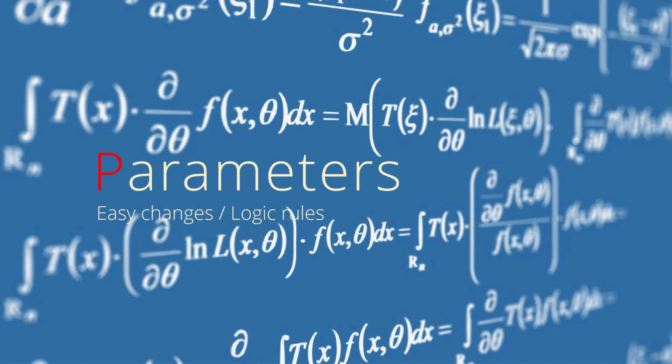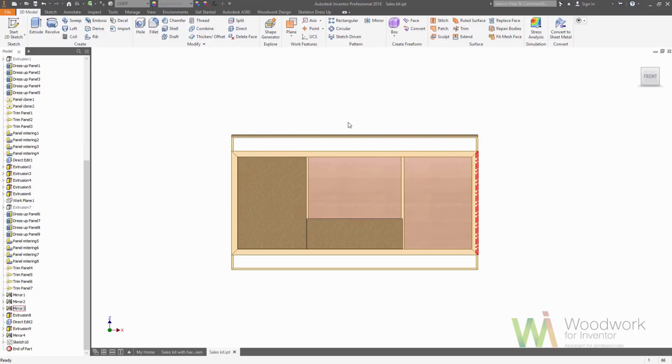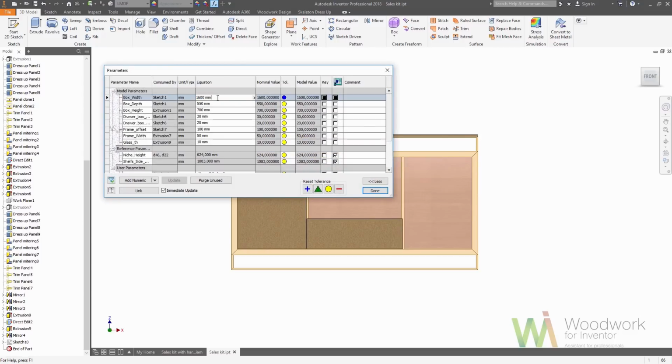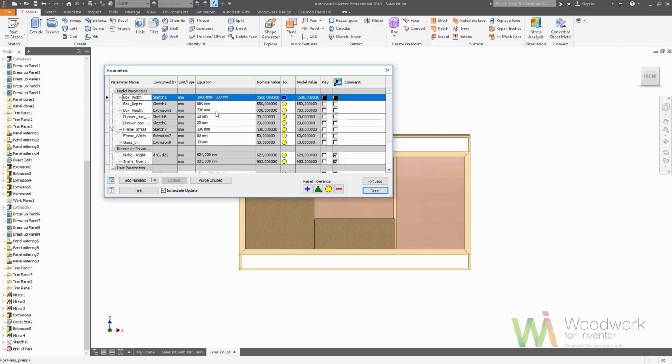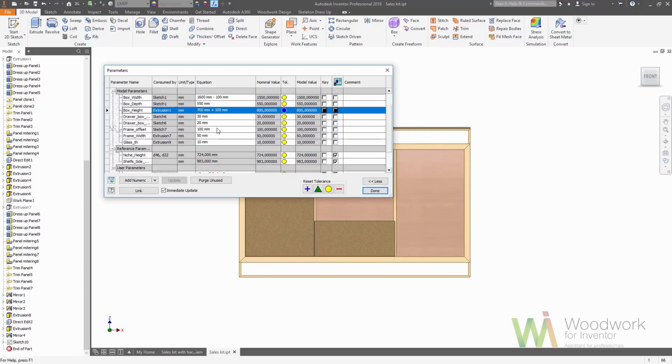Now let's speak about something else, about the parameters, because at the very beginning we start our design using parameters. This means that we must have some easy way of changing the model. In fact, we have those tools. Because the model is skeleton built, we can just say, okay, I want to change some parameters in the skeleton level. Maybe I want to change the width, shrink the model a bit, but add some height. Yeah, so let's make our model a bit taller.